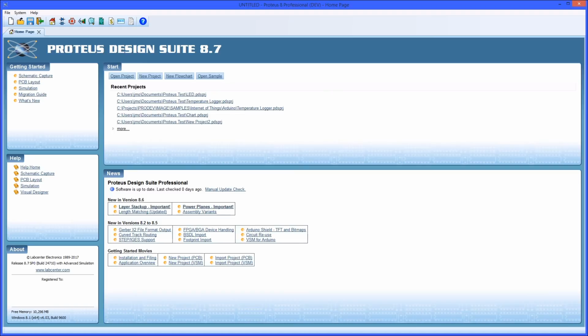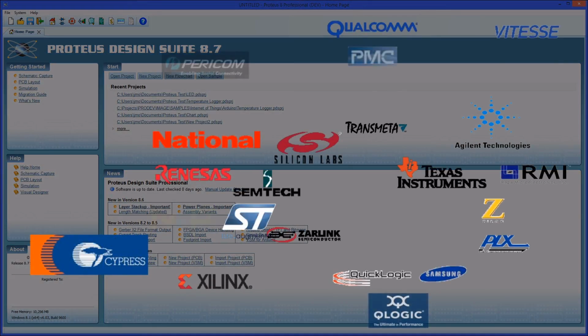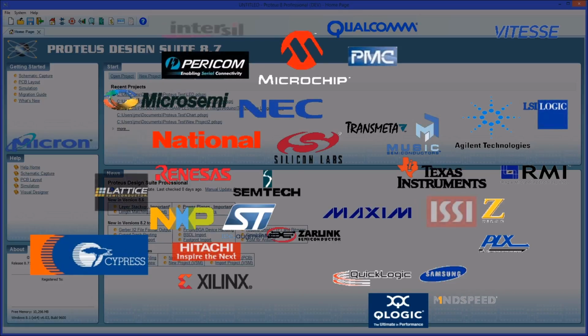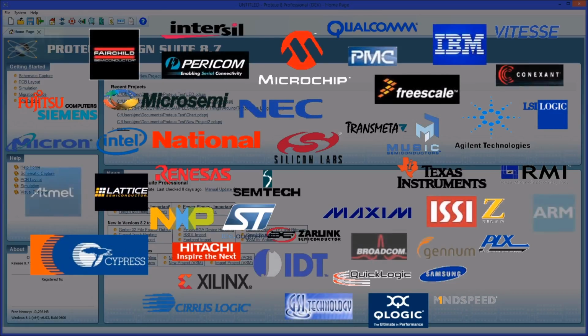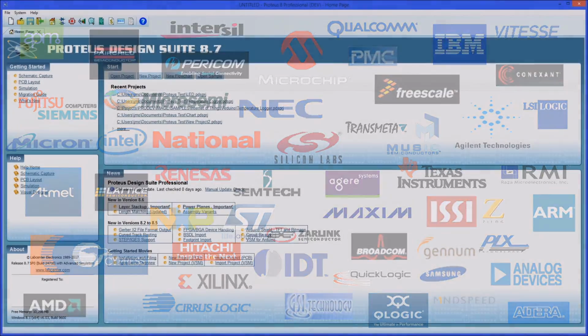The BSDL file format is a description language designed for electronic testing using JTAG and is supported by a large and growing number of silicon vendors. The format includes pin names, their electrical type, and also their mapping onto pads in a footprint. This makes it very useful when creating schematic parts in CAD software.